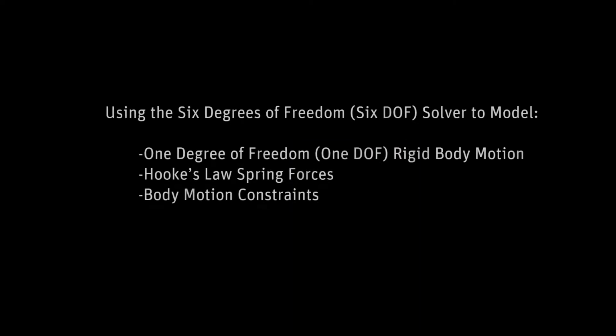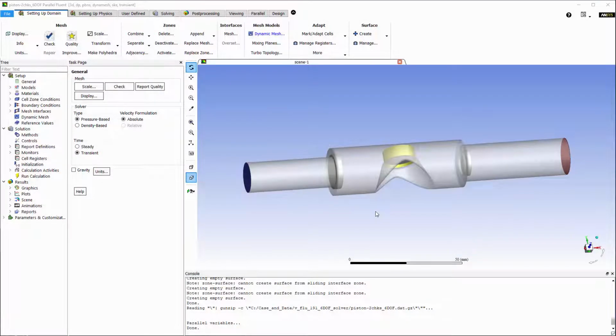In this video, you'll learn how to model 1 degree of freedom rigid body motion in a transient fluid simulation using ANSYS Fluent's 6 degrees of freedom solver. This solver allows you to account for external forces and moments exerted on a moving body by the flow, and its 1 DOF settings allow you to easily include spring forces and limits to the range of motion. This approach can be used in modeling flow-driven motion of spring-loaded valves.